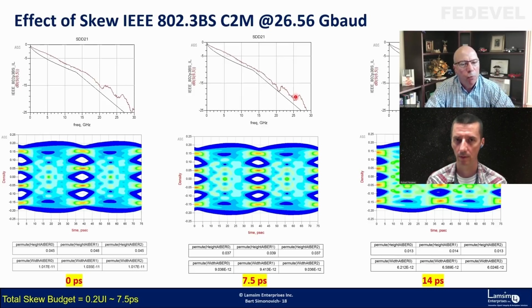So you have like 4 ports on the trace. So 2 at the input and two probes at the output. So you measure them together? Yeah. The VNA does the whole measurement. Oh, I didn't know you can measure differential pair with VNA. I thought you only can measure like single-ended signals. Oh no, they have what they call a 4-port VNA.